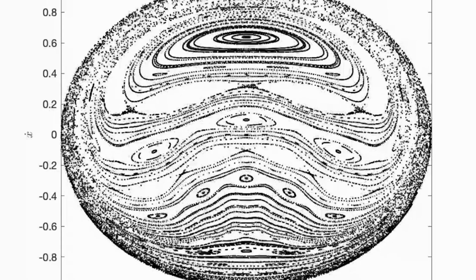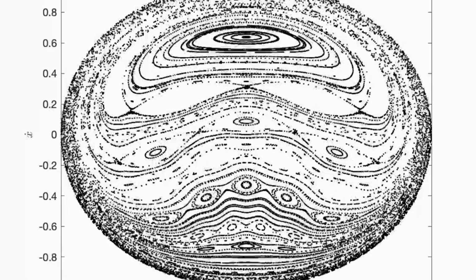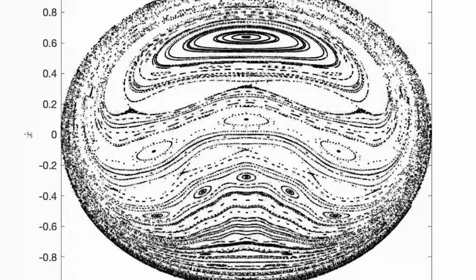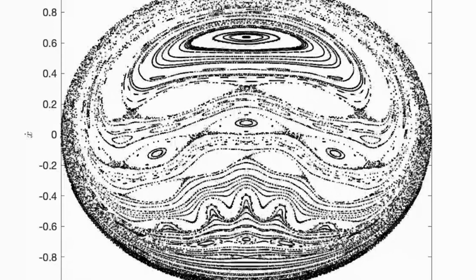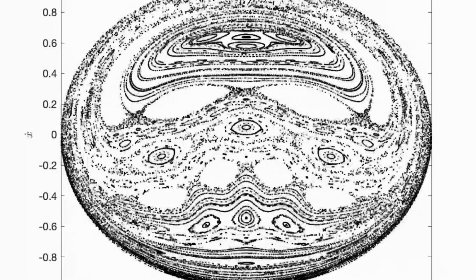Looks like a destruction. And we found that around 0.37 there was a very interesting 3-to-1 internal resonance that popped up and consistently happened. You can see that is indeed shown here. There's also the emergence of a 5-to-1, again being another odd order. Again, this is a harmonic system, so a lot of these types of internal resonances may not appear in a damped system. We're just going to keep going.